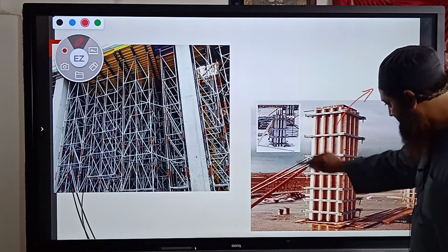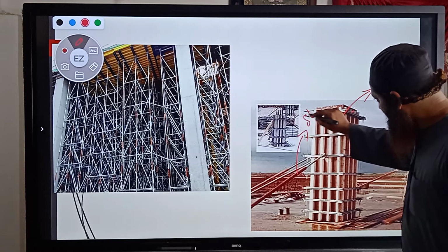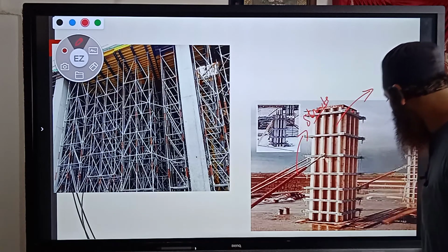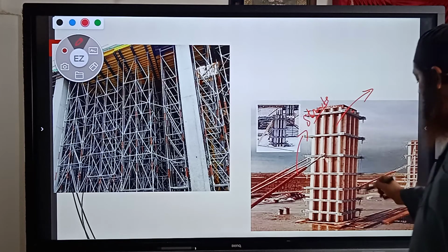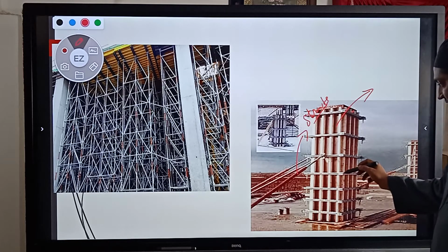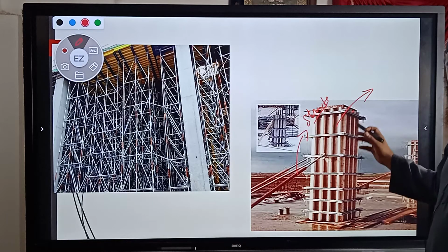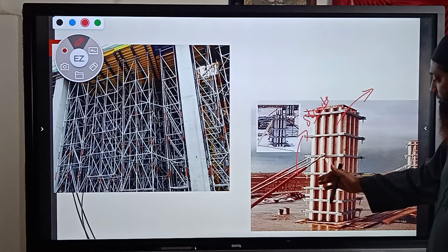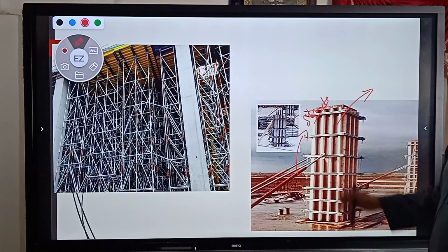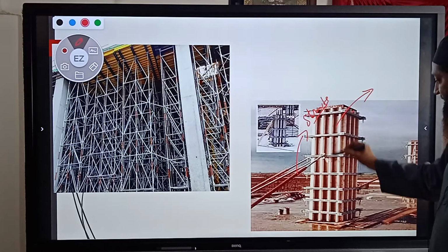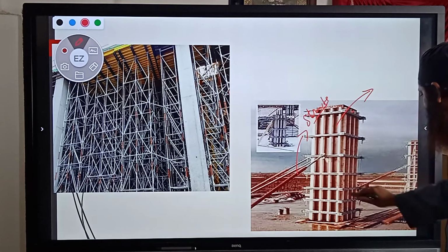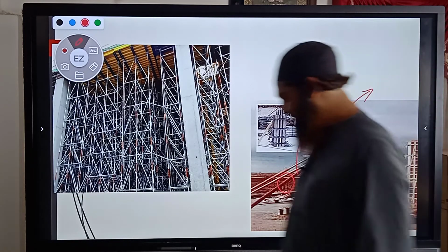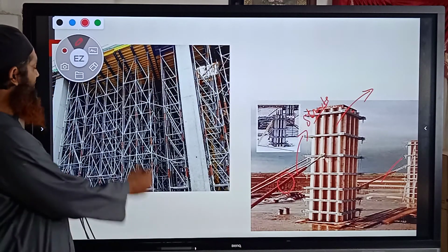You can just see these are the struts we had seen here. These are the struts which are being used just to resist. You can just imagine how big this column is, and imagine when a huge amount of concrete is poured into it, what happens? There are chances of this formwork coming off. So just to reduce that failure, we provide these struts here. You can see this strut, this strut, this strut. The same way, you can see the formwork and how they are casted here.